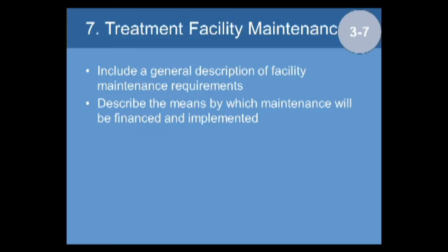But the harder part is who's going to be responsible, and the PCRs do require that be very clearly defined. Relatively easy for a commercial development where it's one owner. Gets a lot more complicated for subdivisions where you're going to have different property owners, and you need to make sure that with the successive iterations of who owns that property, particularly if it drains somewhere as part of either a commercial development like a shopping center or as part of a residential development like a subdivision, that responsibility runs with the land.